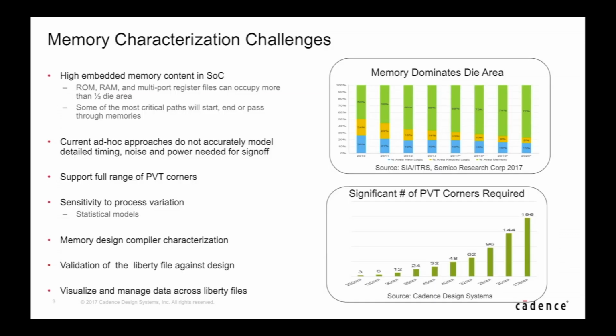Some of the main memory characterization challenges is that memories have become ubiquitous in the design. They occupy at this point 75% or more of the die area, and the current ad hoc solution to accurately model such memories are not good enough, and they don't contain enough details about the timing, the noise, and the power characteristics that are needed to describe these memories and to be used in a sign-off solution.